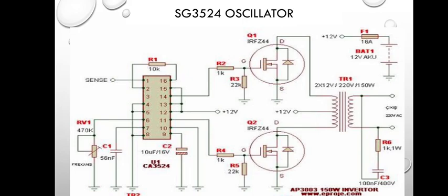Now you can see a fuse at the top right corner, 16 amp fuse. You can use a fuse, but that will depend on the capacity of the inverter. That is what will determine the fuse you will be using. So I'll also show how to calculate the capacity while designing an inverter: the capacity you will need, how many MOSFETs, and the size of transformer for some capacities and calculations.